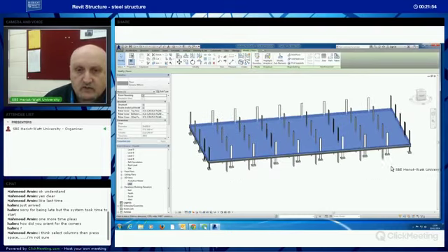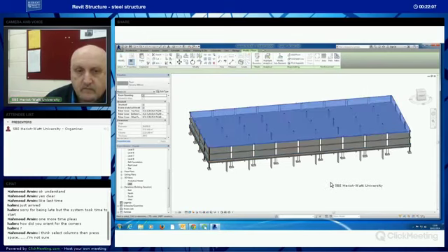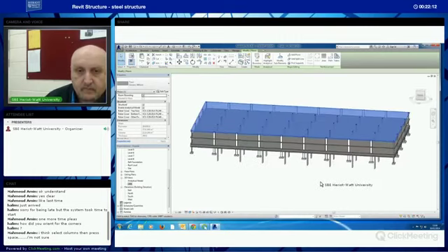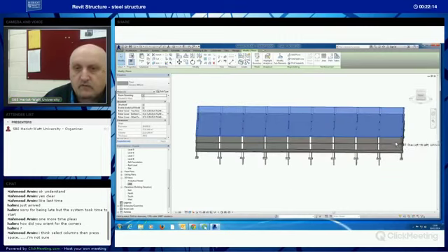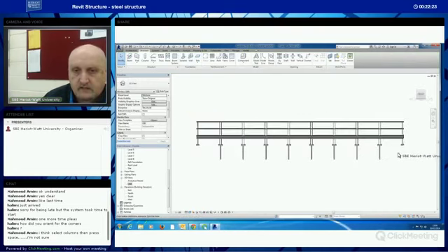I'd like it to be selected, so if it's not selected when you do this, select it at this stage. I'm going to copy that floor. I don't want to model it on every level. I'm just simply going to copy it up onto the clipboard and paste aligned. Now it's on the ground, so I'm going to put it on 2 of these levels. And we're beginning to get what looks like a building. Now I'm going to foreshorten this floor profile as I copy up the building. I'm going to select just the columns.